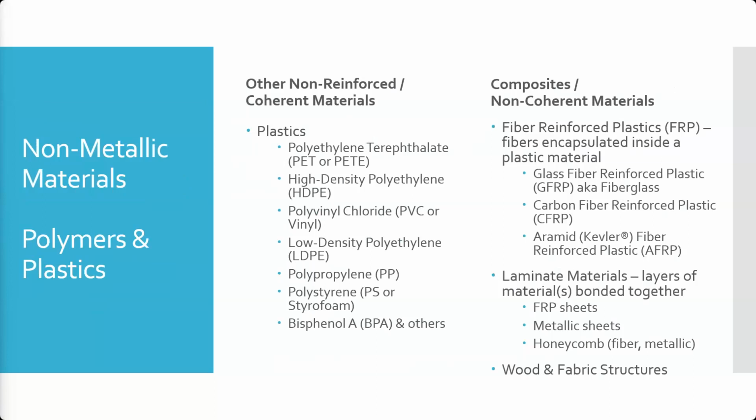The Saab 340s I worked on used a metal composite skin. The skin was not a single layer of metal, but rather a couple of thin layers of aluminum that were bonded together, and then honeycombs, like fiber metallic honeycombs. You all use fiber honeycomb, right? Almost looks like a papery honeycomb, right? But they make aluminum versions and titanium versions of that as well. Often used on engines and stuff like that.